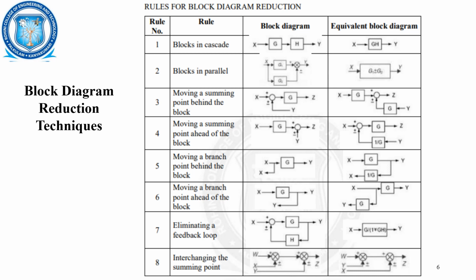If it is a positive feedback, that is both plus terms in the comparator, then you will have g divided by 1 minus gh. And if we interchange the summing points, suppose it is w and x here, and here we are getting the value of w plus or minus x along with y. If you are interchanging, then it is w and y with a combination of x. Obviously we'll be getting the z value to be the same.